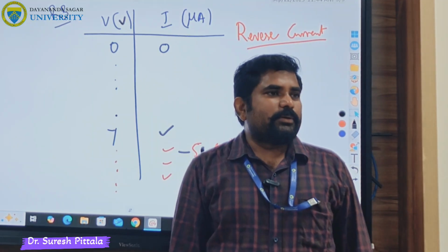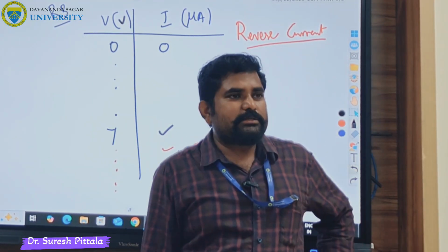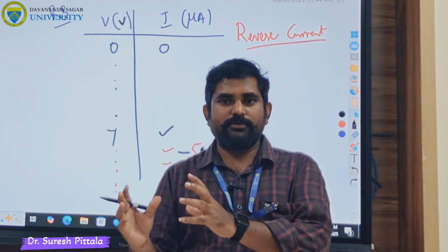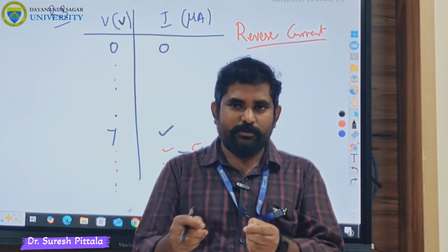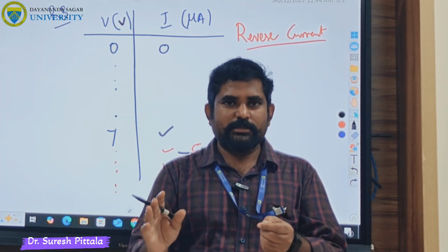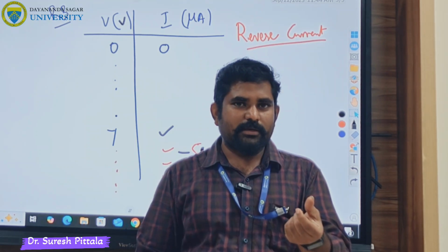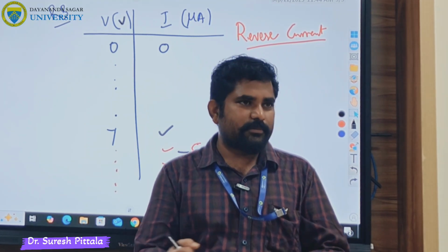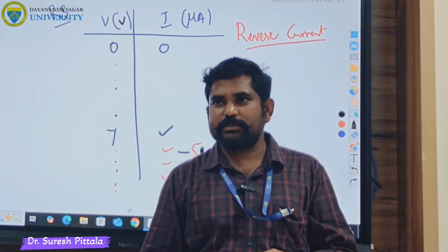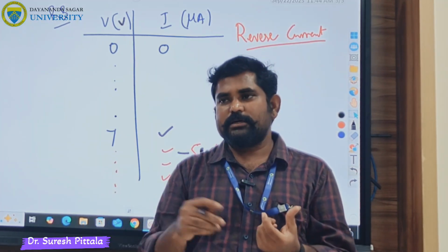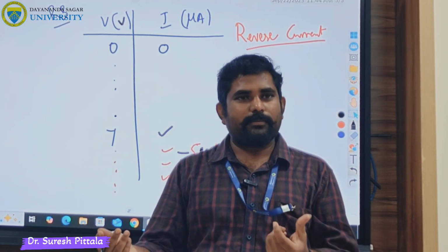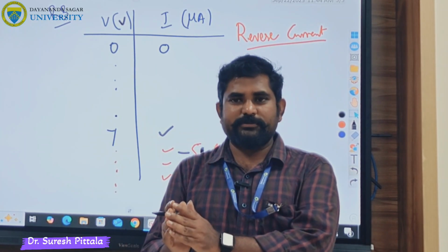Right? So in both the cases, our experiment is done. What we are verifying is, we take a Zener diode and connect it in the forward bias first, a simple connection, then slowly increase the voltage. You need some kick to send the electron to the other side. Slowly increase the voltage and see how much current is flowing in the forward bias. Once the current reaches 20 milliampere, for the safe side, you stop the experiment.